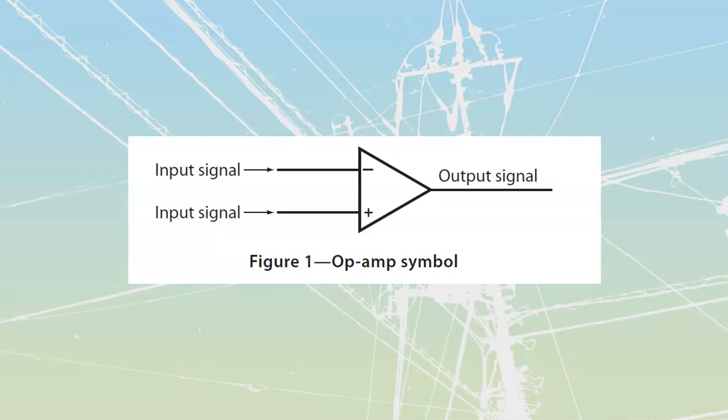Originally, these things were used for high gain DC amplification. It is going to be similar to what you have learned about transistors and FETs in that it is going to take a small signal but make it larger, but these are going to be much more stabilized than using just a single transistor. There's this whole science that goes around transistors and transistor biasing and balancing and using multiple transistors, etc. What we have inside of an op-amp is a ton of transistors that are all going to get connected together properly, biased together, properly tuned, and then put out in a tiny, tiny little package.